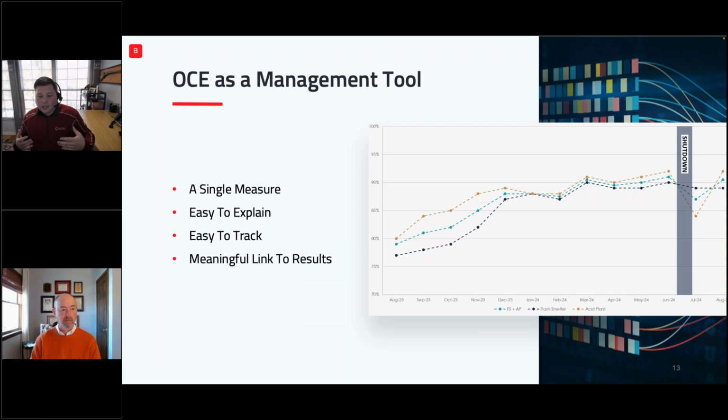You can start to understand that when OEE increases by a certain amount on this machine, we gain X number of widgets per hour, increased production, or quality improvements, or dollars, whatever these things are. And so you can use this as a management tool to track not only individual loops, but to aggregate that information up to units and areas and plants and regions and divisions, and start doing site-to-site comparisons.